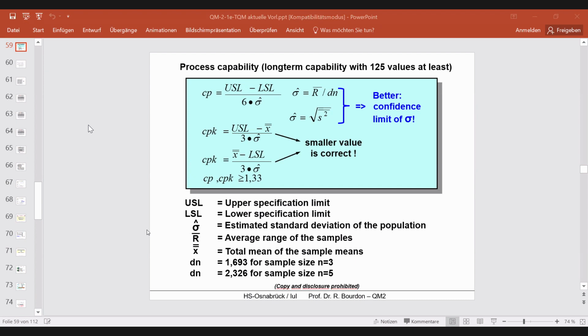to let quality charts run in the production, and from time to time, one time a shift, two times a shift, you take samples out of the production, and then you measure the parts, and you put the values into the quality chart, control chart.